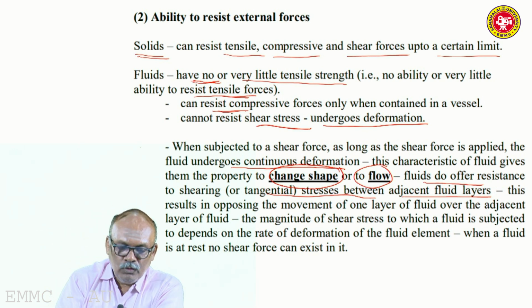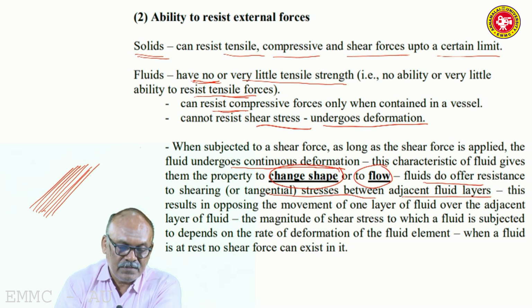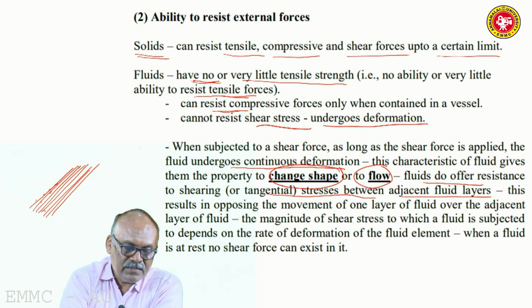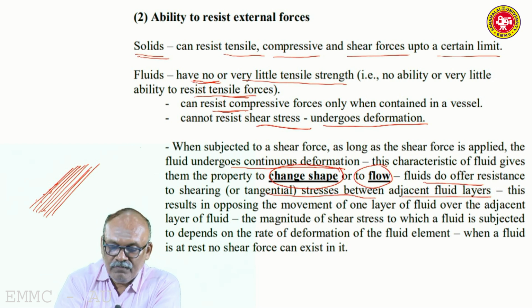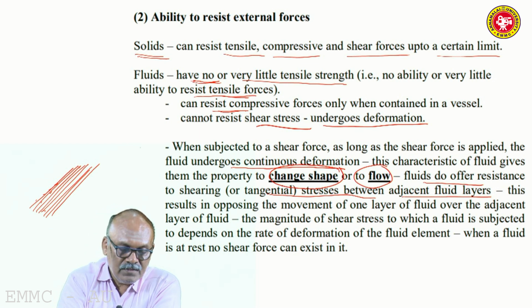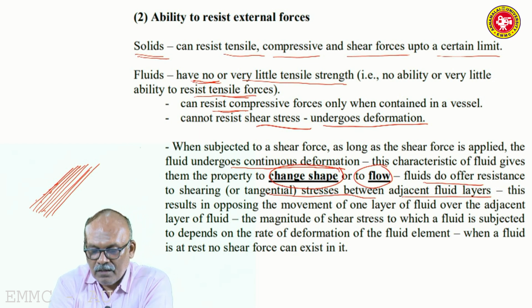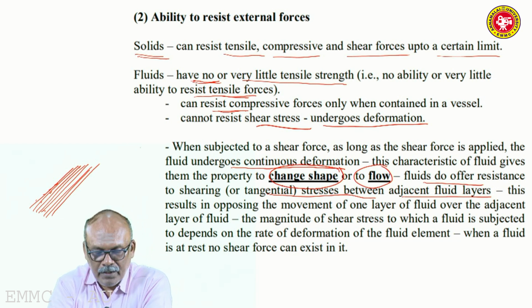Say for example, if you assume the fluid to move in layers from one point to another in parallel, and each layer is composed of a number of molecules, between adjacent layers there will be some resistance because of the shear stress induced, and this shear stress will actually oppose the movement of one layer of fluid over the other layer of fluid.